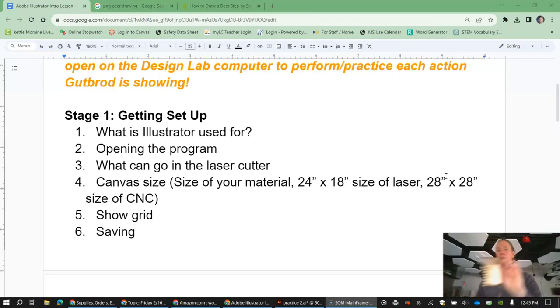But we have, of course, different thicknesses of wood. The laser can cut through 1/8 inch thick wood, and it can of course etch on all kinds of different woods. And we can cut through 1/8 inch thick plexiglass. We can go up to 1/4 inch thick plexiglass, but pretty much everything that we have is 1/8 inch thick plexiglass. We can of course cut through cardboard and so on, but we can etch on a lot of stuff, cut through thinner type stuff.